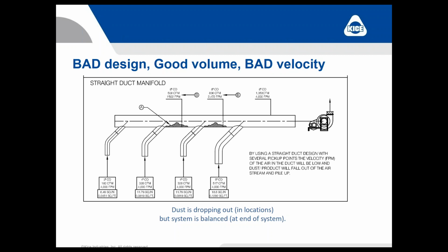As I've stated, that's not enough to keep it. So what's it do? It lays out in the line until there's enough closed off area so that the remaining area can convey that dust down to the next point. And so you look at this example and you wonder, this is why you have dust lying in your dust control lines, and you thump them and they sound solid. And that's probably a good indication of what's going on there.